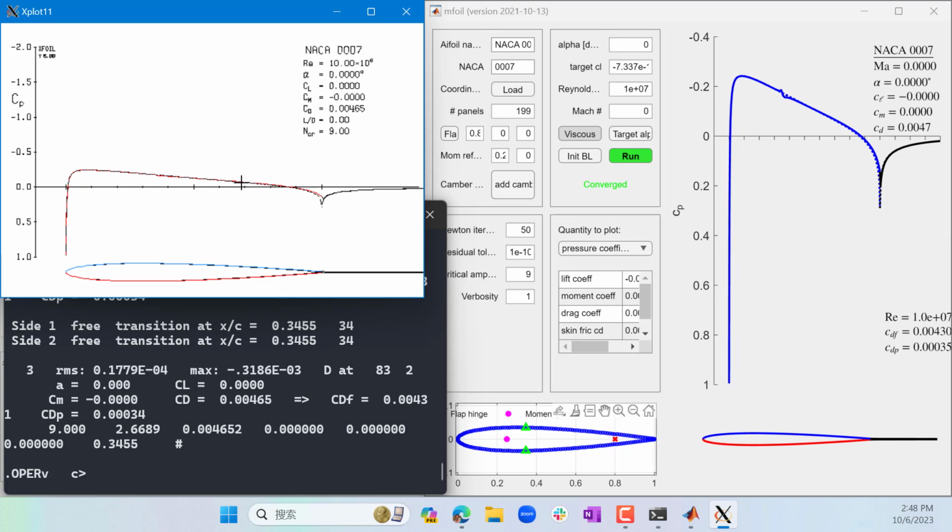We're going to see this is not going to be exactly the case because the flow is going to transition to turbulent boundary layer, and the turbulent boundary layer is going to behave differently. So this is not exactly true, but it is true for the front part of the boundary layer before the flow transitions. Actually, on the right plot, you can see this kink here. That kink is actually a pretty good indication that the flow transitions over here.